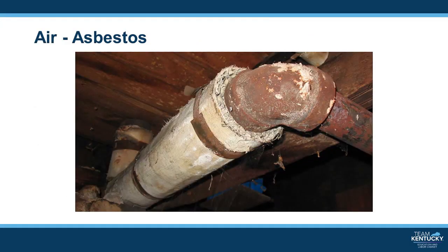As you can see in this photo, asbestos could be found wrapped around pipes and tanks and boilers as an insulation to keep the water and other liquids inside them hot. It might be intact or it might be damaged. It might be broken off and lying on the floor. Your first thought should be, do not disturb. It might be in or near the area that needs to be repaired and welded.